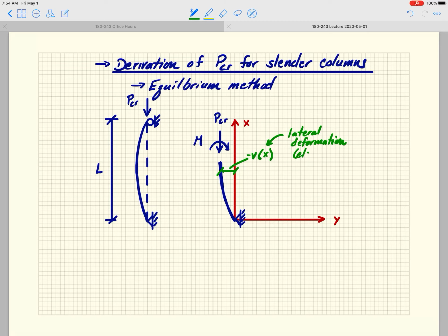And it is also what you had solved for as the elastic curve previously. Now that wasn't with columns, it was with beams, but effectively it was the deformation caused by a moment on the element. So in this case, it's a column. There's a moment on the element that's causing a flexural deformation. That's exactly the same thing as if you turn it sideways and call it a beam. Effectively nothing changes there.